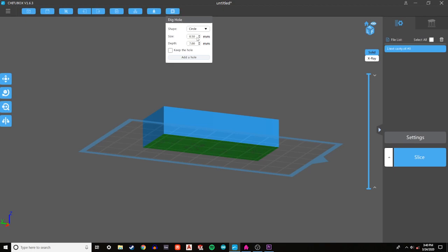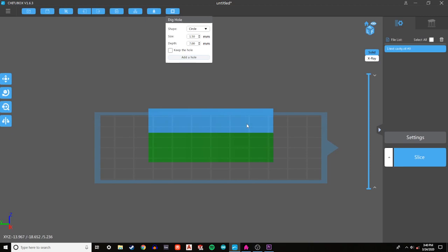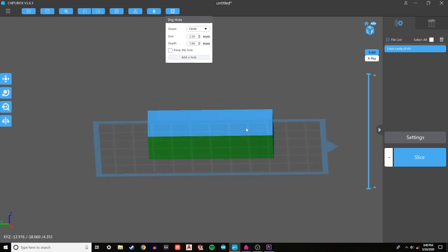Look at that, I used a 0.5 millimeter hole, and that was just too small. So I'm going to raise this to a 1.5 and just see how that works. I already have this set. This worked for this particular model. You're just going to have to play with this until that bore length is long enough to reach your cavity that's in here. So sometimes it takes a couple tries, but it will work when you have it set correctly.